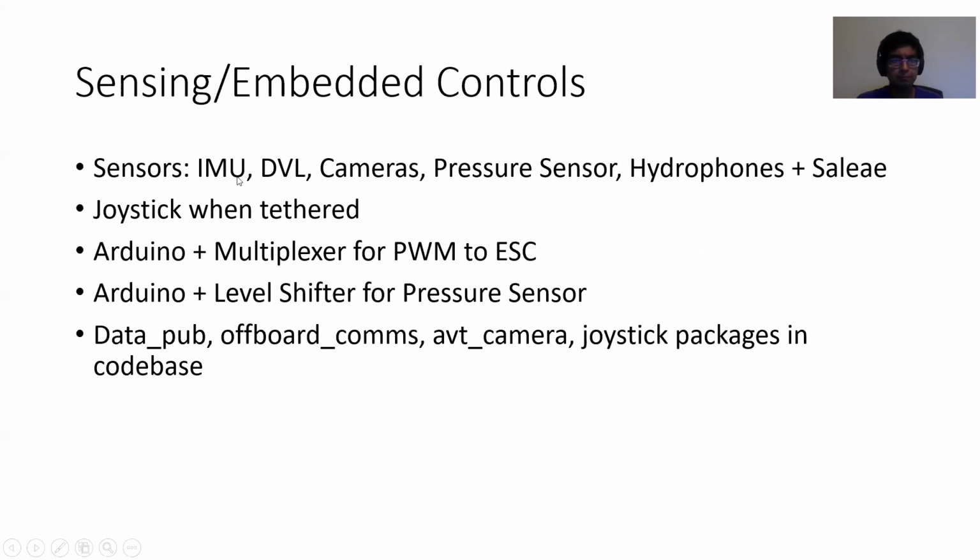The IMU stands for inertial measurement unit. It provides the orientation of the robot, specifically the rotation of the robot, roll, pitch, yaw axes, so on. That helps with state estimation with CS. The DVL provides absolute velocities for the robot, like how fast the robot is moving in each of the directions X, Y, Z, also used in our state estimation program.